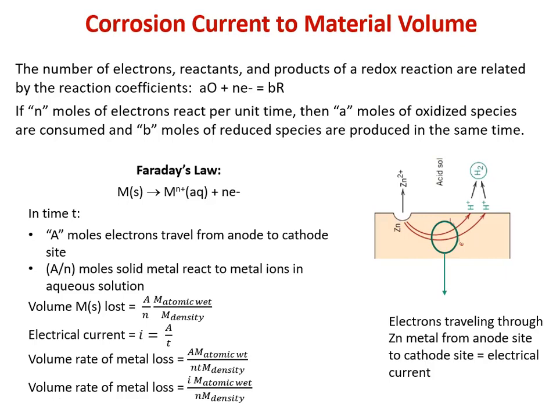So the quantity that we need to introduce next is corrosion current, the actual number of electrons that are flowing as a result of these reactions. And in metallic corroding systems, that is literally a flow of electrical current from an anodic site to a cathodic site. Lucky for us, we can actually directly relate that flow of electrons to the rate of loss of material. And so if we have a way to measure that electrical current associated with the corrosion reactions, that corrosion current, we can directly estimate the rate of metal loss. And that is actually frequently done both in the lab and the field.